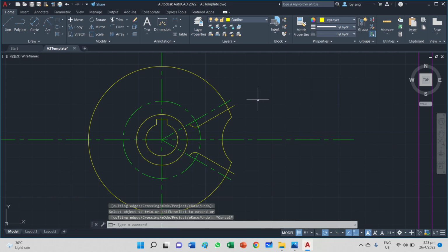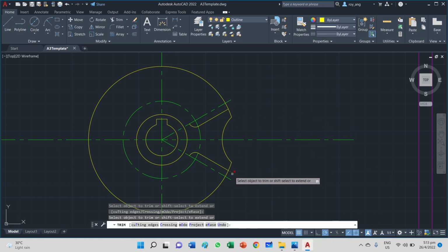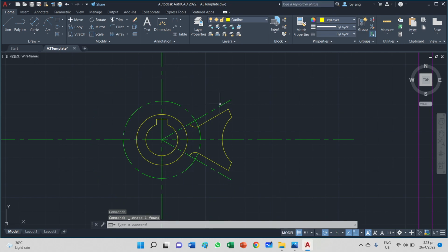Now what happens is, let me think. Okay, I can trim the outside as well. And I could even trim this and this. Then you press escape, and then I select the overall arc and press delete. So I don't need to keep trimming and trimming because it intersects every segment of the quadrant. Okay, so now I get this outline.